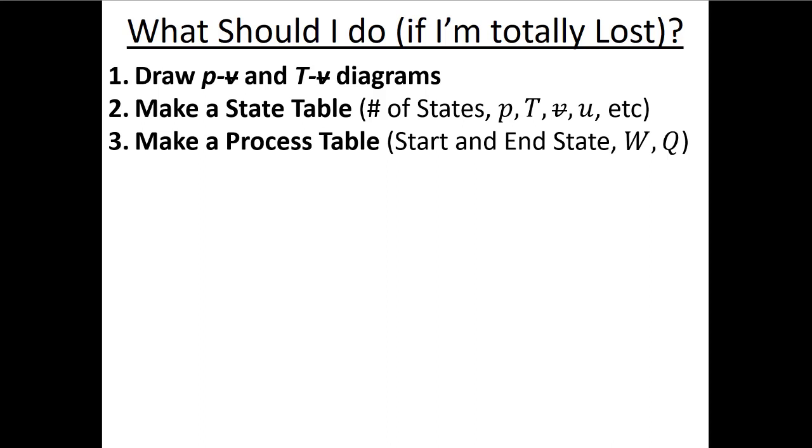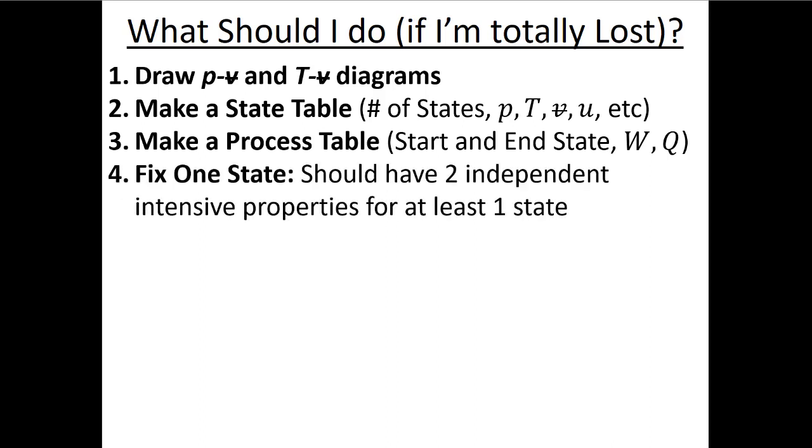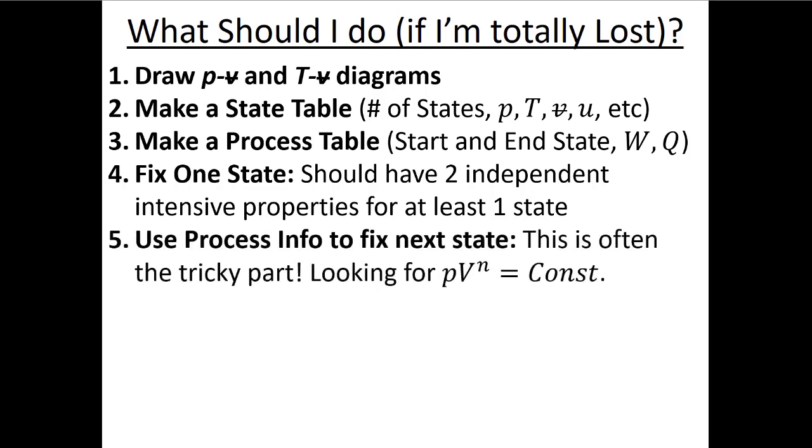So if you can say, okay, I need the first law, I got to ask myself, what's the fluid? And if it's water, what's the phase? And if it's air, is it constant or variable specific heat? I got this state table, I can start to write things down. Sometimes you just get a little bit of inertia and then that'll let your instincts kind of kick in a little bit, right? So now that you have this state table, you can have your symbolic solution for the first law. You can see where you can start to fix states, right?